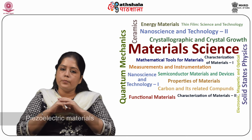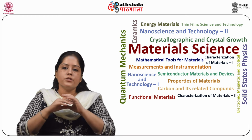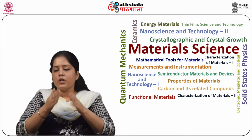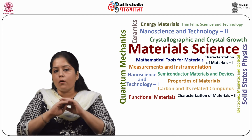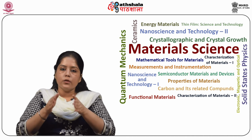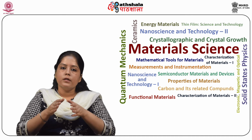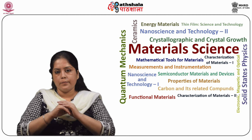Third are the piezoelectric materials where heating produces the change in mechanical stress, which in turn changes the surface charge density. Fourth one is a non-piezoelectric material where thermally induced non-uniform deformation can also produce the changes in surface charge density.